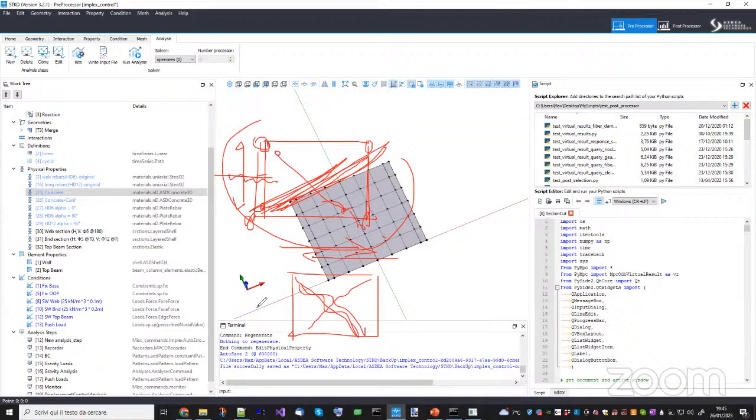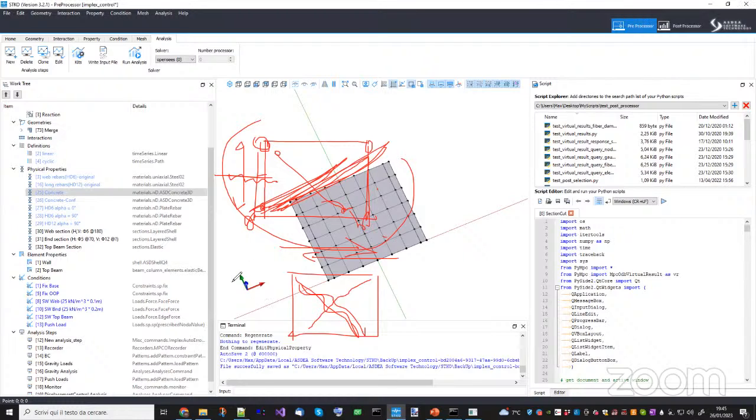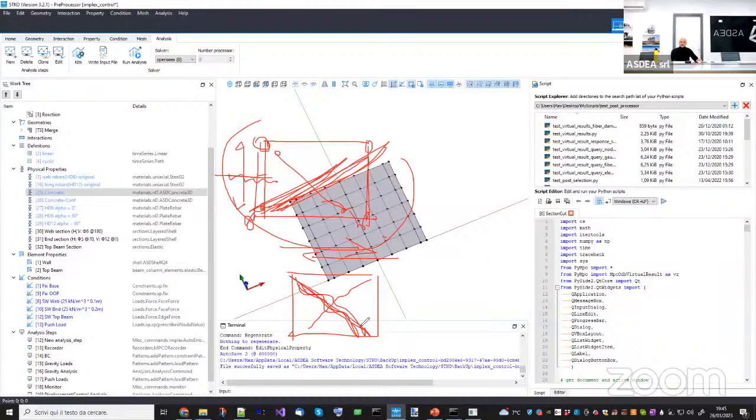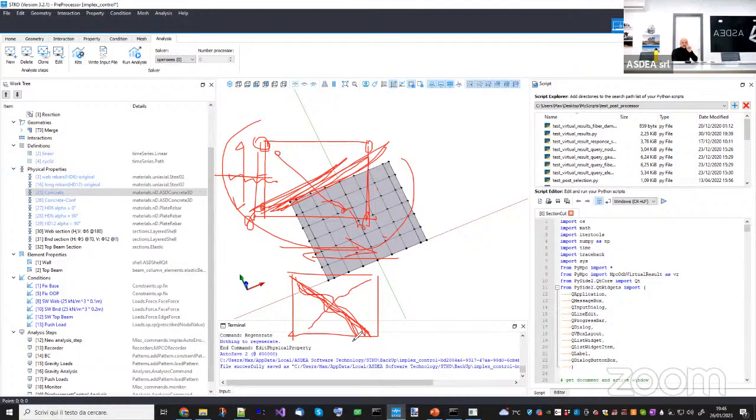Yeah, no, I understand. Yeah, there are two different things. But let's see what you drew there, right? Look at the crack that you drew from the top left to the bottom right. When you open these cracks in your model, automatically you will have a weakening of the FC prime, or of the concrete strut that is in that same direction as the crack, right? Yes, but it's not like that actually.